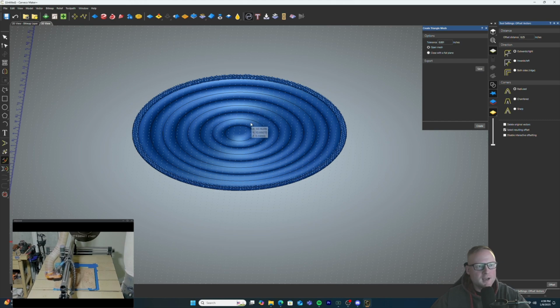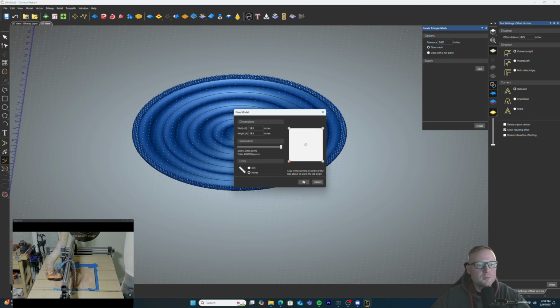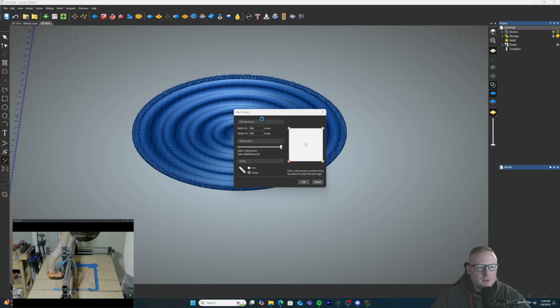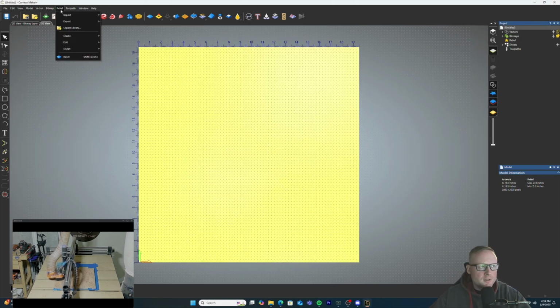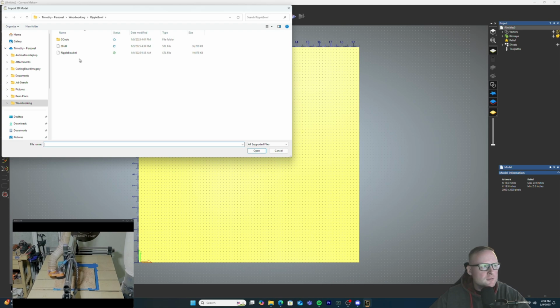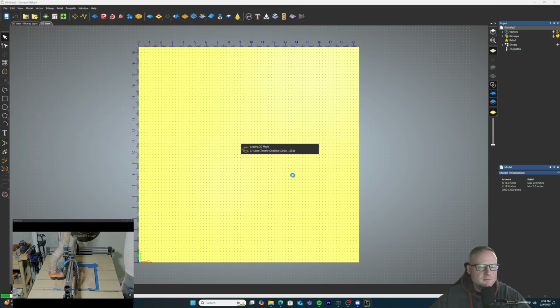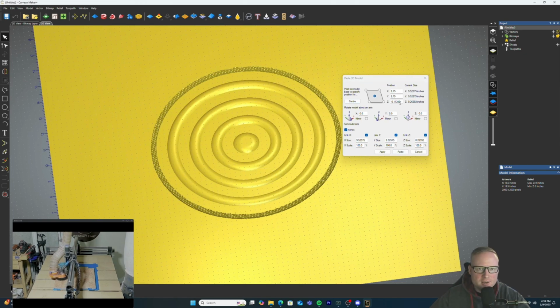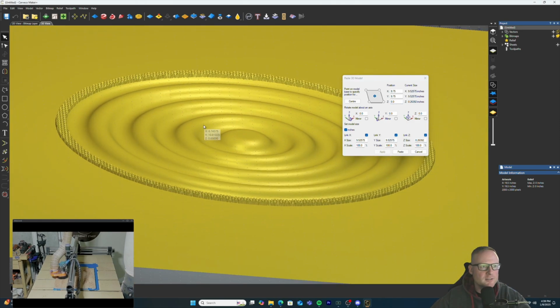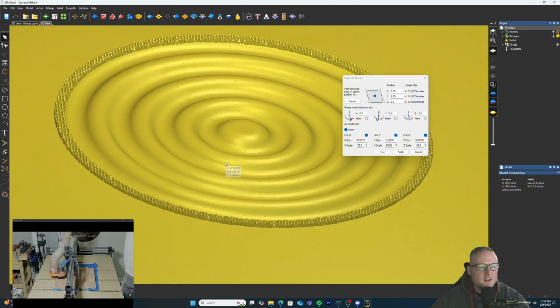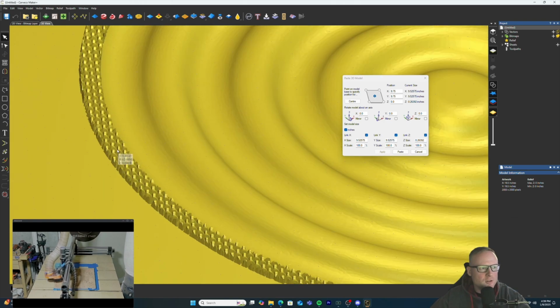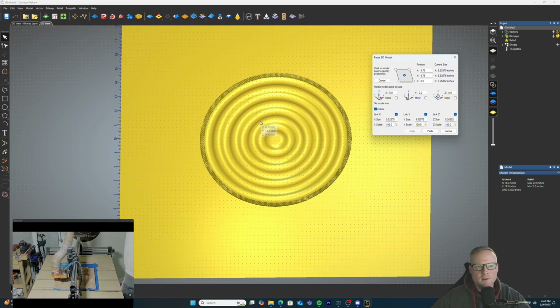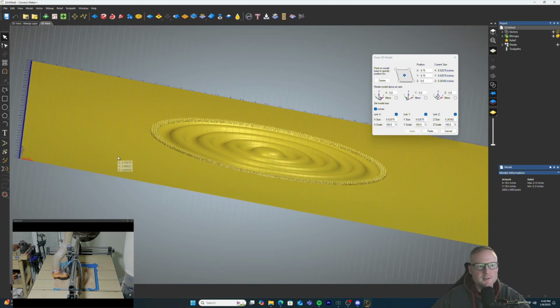So with that 3D mesh that you created and you saved, you can actually go ahead and open up a whole new model. Click on relief. We're going to import 3D model. Here is the file that I just saved. And as you can see, it has my image here that I created. Go ahead and modify your Z to 0 so that way you can see the full image. You can see the ripple effect there that we created along with that textured pattern. Before I were to actually cut this out, I would probably lower this texture down just a little bit more. So that's it. You can use this method to create and manipulate vectors into 3D images, however you see fit.